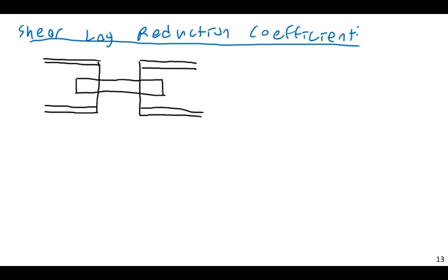Stress flows. Stress moves. It bends. It flows around shapes. If you took mechanics of materials, you saw this. Stress flows. It moves around obstacles. If it has to go around a hole, it bunches up near the hole. You get stress concentrations at certain locations.